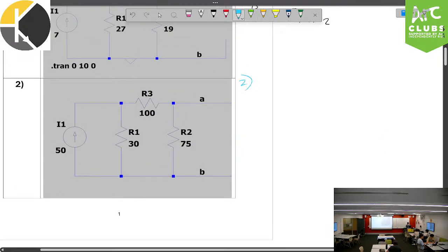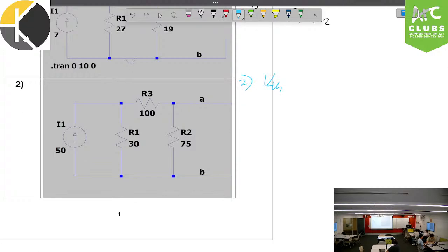Okay, so Thevenin, easiest way in my opinion to find this is you go and just calculate currents through. Okay? You could do a current divider right here, followed by a voltage divider to find VA. Since in a lot of these scenarios, VB is just, we're going to take that as 0, right? So these are the things we can do.